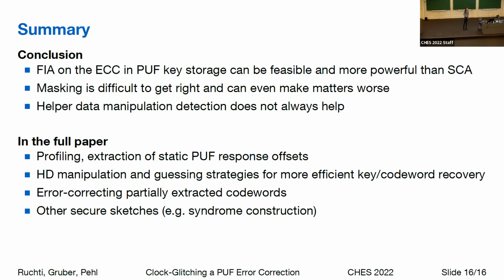It wouldn't have been that hard. So we already have a PUF implementation we could have used. Basically, it's just that the PUF typically is a slow operation, and by the time the decoding starts, you would expect it to be finished. Or if it's running in parallel, then you might change a single bit in the PUF, and it wouldn't matter that much. So it basically doesn't matter in the end if the PUF is there or not. And if you use a register, we also have the benefit of being very flexible in experimenting with random keys.